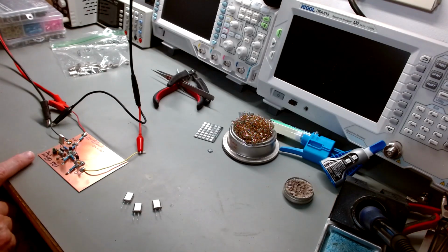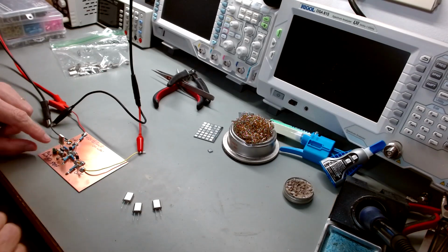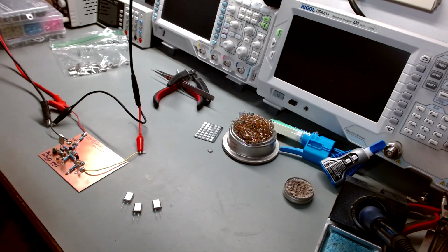I would try to use something that doesn't have a lot of capacitance in it. The whole idea is you want a clean short with almost no capacitance. So this little button is good because it's surface mounted. Everything's short: leads are short, contacts are short, so that helps. This is how it works, and this is a handy device to have, and it'll help you get this done. If you don't have the spectrum analyzer or the frequency counter, that'd be okay.